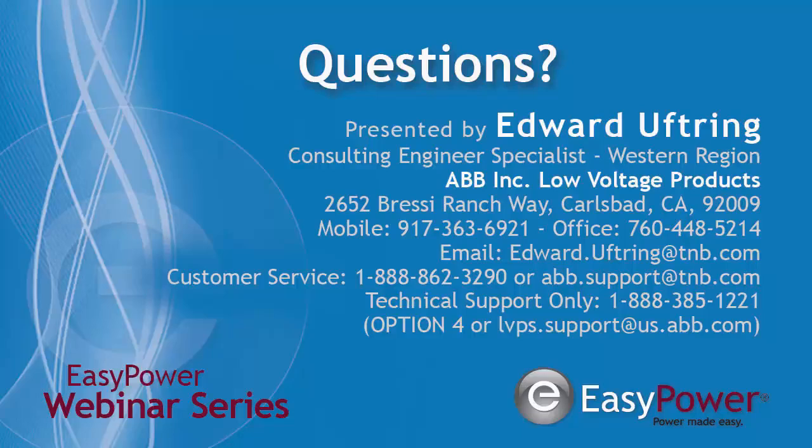We do, however, have load ratings on our breakers because we know it's an application that is being used. There's some power plants that I'm already in conversations with, and our new breakers do have, I want to say, close to 15 to 20,000 power cycles that you can do under full load. However, again, it's not what you really want to use as it stresses the breaker, and it's a lot harder to replace or service a breaker than it is to service a switch, a disconnect switch, a contactor, or something like that.